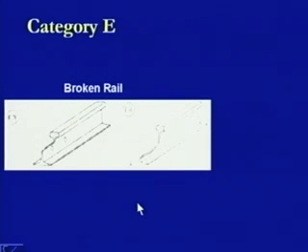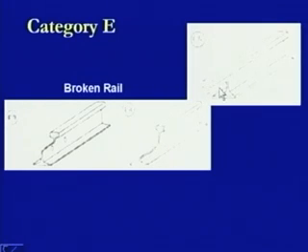Now, in the category where the broken conditions are there, we see that this is how all of the rail section has broken down. Then this is the distance by which it has gone out, and still we have found that there are the holes. So, this material has gone away, whereas in this case it has gone in such a way that even these holes are no longer here, and it means the fish plates also have gone out. In this case, though the head has remained intact, its bottom has gone away. So, it has broken at the bottom shape.